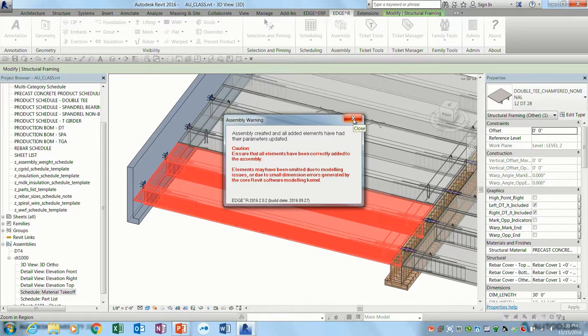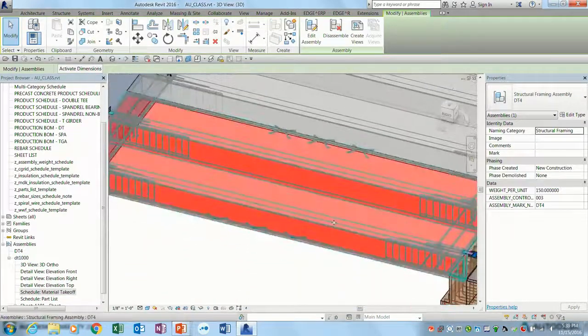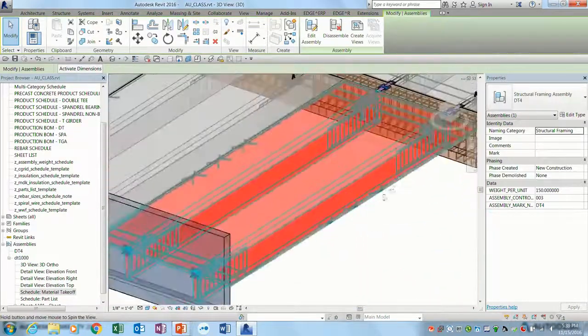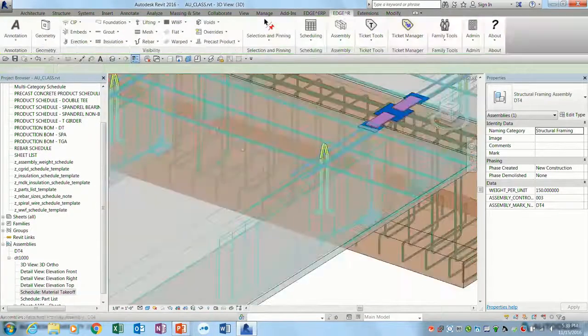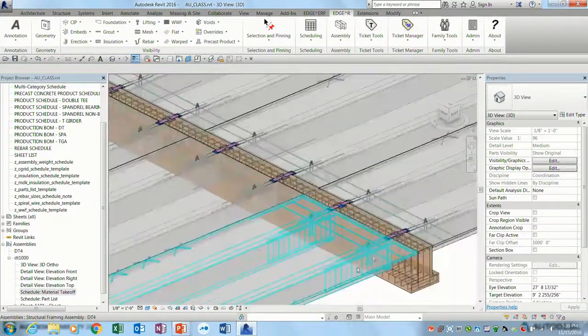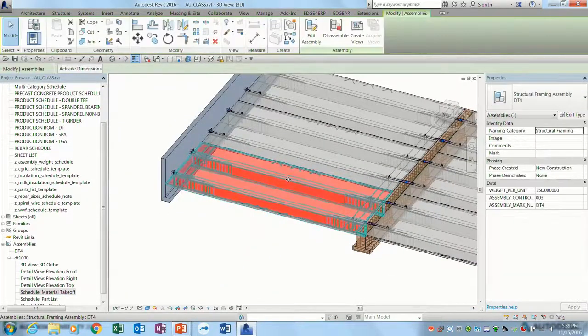We just utilize the fact that all of those things create a geometric interference with that structural framing element. In modern day, you could utilize Dynamo for the same thing. You could leverage a Dynamo script to identify those interfering pieces and collect them up into part of that assembly. So we've just automated that process to make it really quick. Click the piece, click the tool, done.